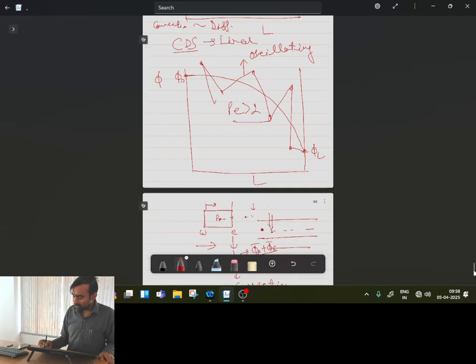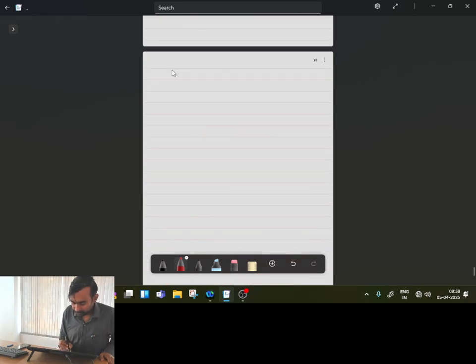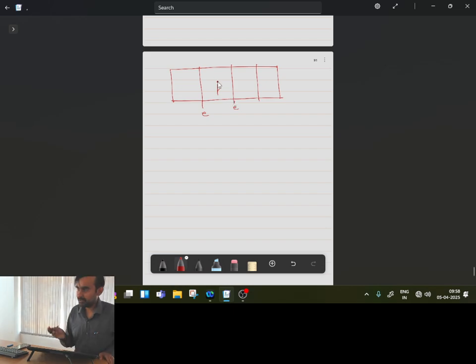We can take certain schemes where, for estimating the value at every face because of the convection effect, I will give preference to the upwind direction only, and these types of schemes are called upwind differencing schemes.